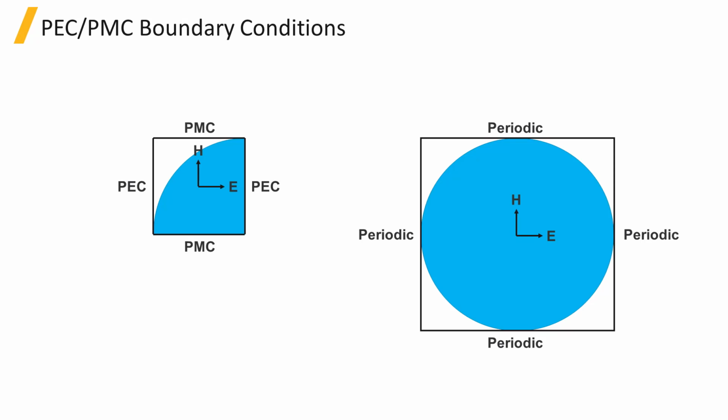For example, if your source is at an angle, the fields will not be symmetric. The choice of PEC or PMC on the boundary depends on the source polarization. Determining the correct option can be tricky. To ensure you have the correct settings, run the simulation with and without taking advantage of the symmetry. You should get the same result in both cases.